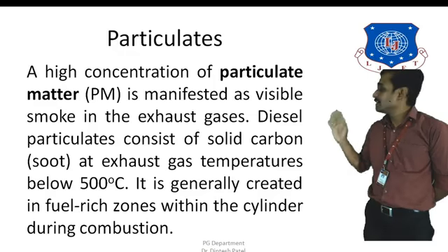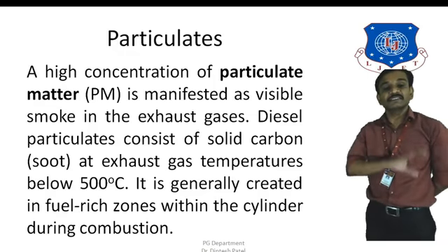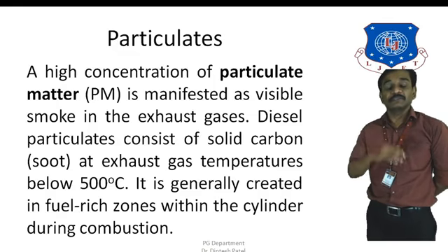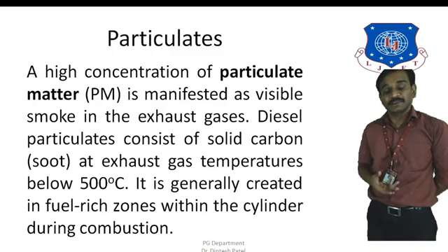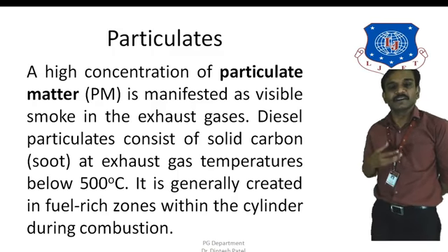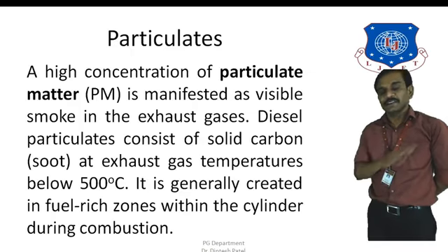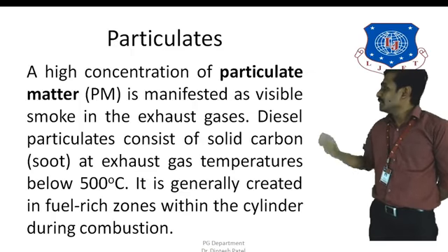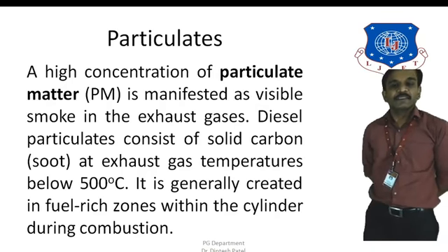It is basically created in a fuel-rich zone within the cylinder, especially during combustion, and you observe the highest amount of particulate matter during the initial startup condition, when the vehicle is running under load, or when the vehicle is going uphill. So this is the last emission of the SI engine.